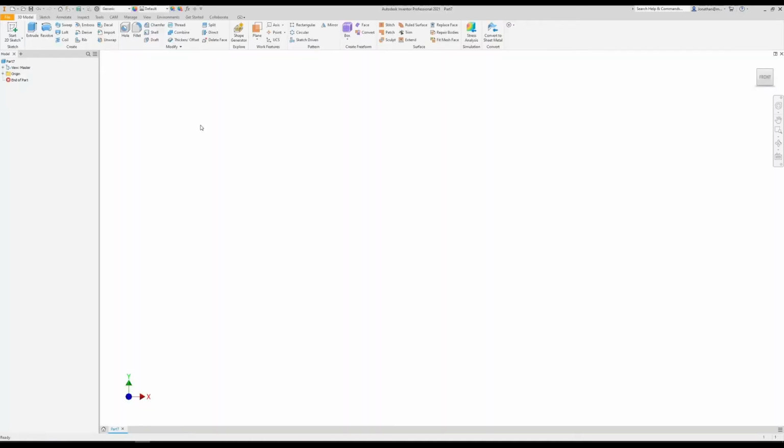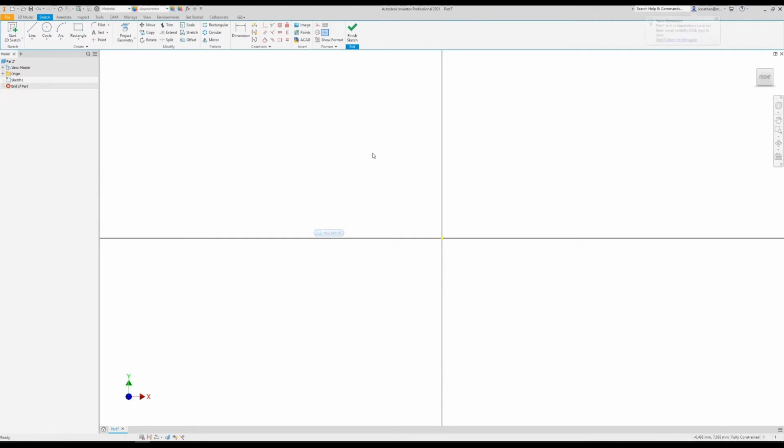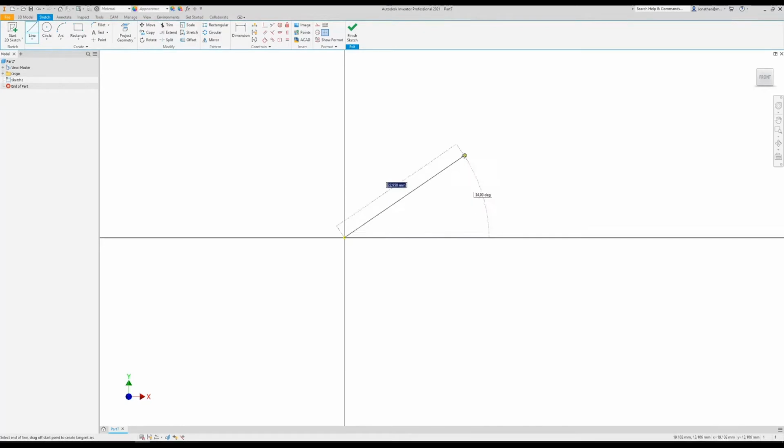So I'm going to create a part, create a sketch, and once I'm in the sketch, I want to draw a line. So I'm going to start my line tool. And when you draw lines, Inventor's got automatic constraints that happen. You'll see if I go to the left over here, just below and to the right of where my cursor is sitting, there's a little vertical symbol, and that's the program's going to apply vertical.